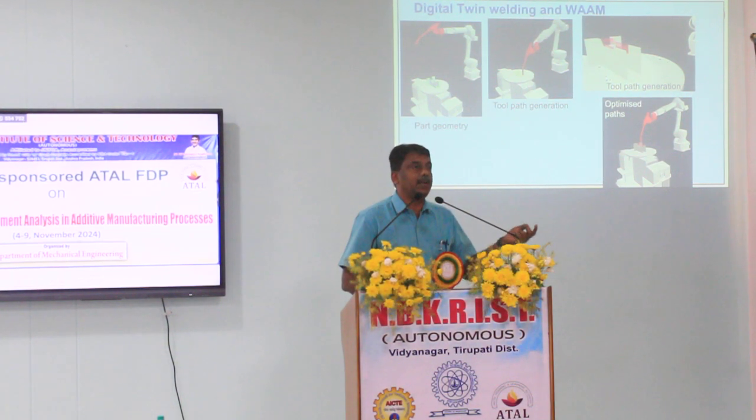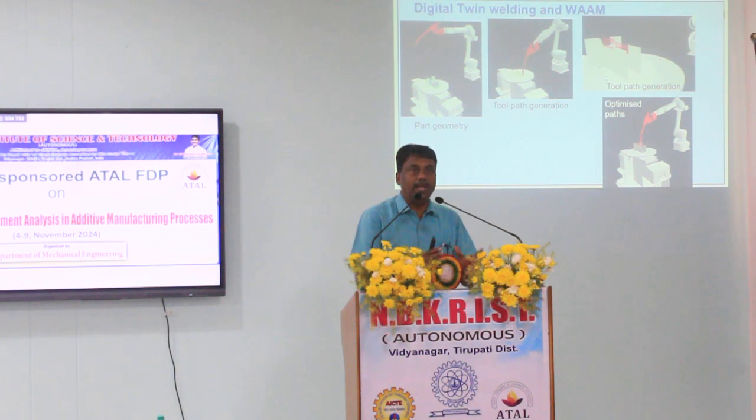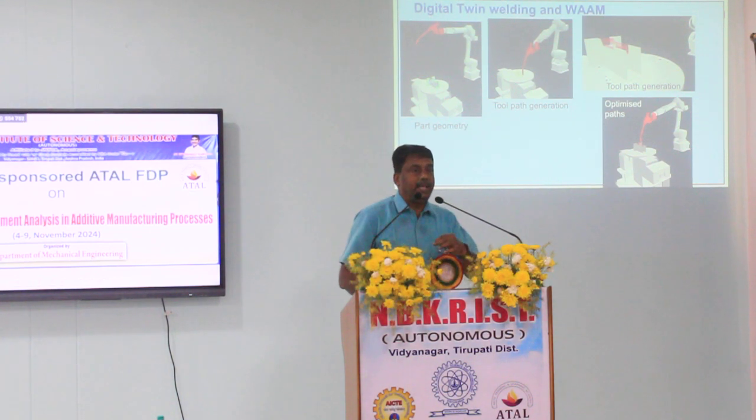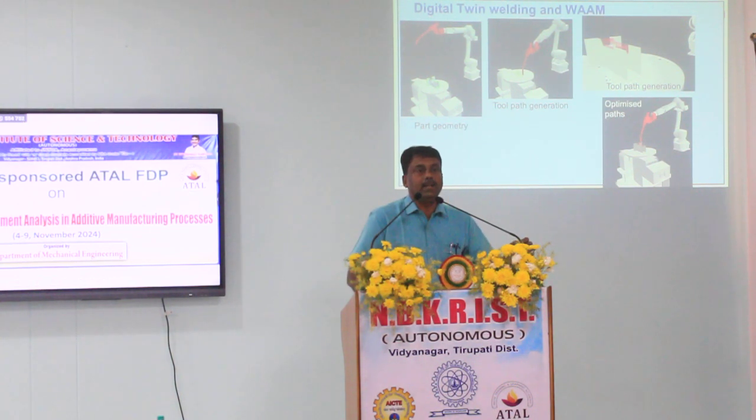The advantage of making the digital twin is that we simulate the actual parts in the computer first, and then generate the scan vectors. Suppose you want to print one layer, for each vector when we print, we also load the welding parameters, what current we need to use to deposit that bead.